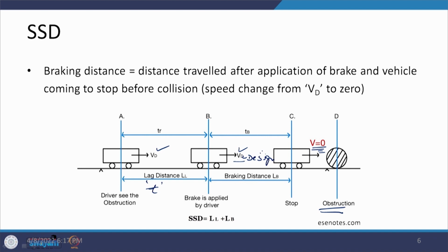We have talked about the design speeds, and if you remember, the design speed in the case of national highways in plain terrain and rolling conditions is a minimum of 100 or 80 kilometers per hour. But when you talk about arterial roads and sub-arterial roads, the speeds become lesser and may be 60 kilometers per hour, 50, 40, or 30 kilometers per hour. You need to revisit those values to understand that.